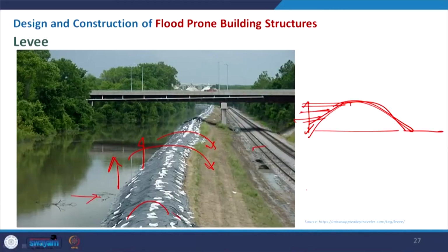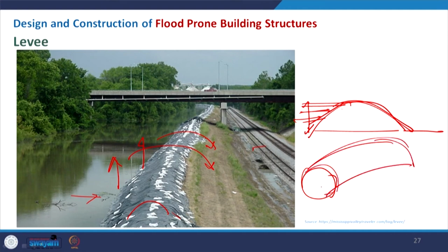Along with that, sometimes we also use a flood barrier. It is nothing but a tube. This tube is filled with water and that will have weight, so that will have enough strength to resist the flow of the water, and that can really help. This is a hollow balloon-like structure. We can either put air or put some water in it, and that will act as a barrier during the flood. So we may have the flood wall as a system, we can use the levee, and we can also have this temporary tube that may act as a barrier.